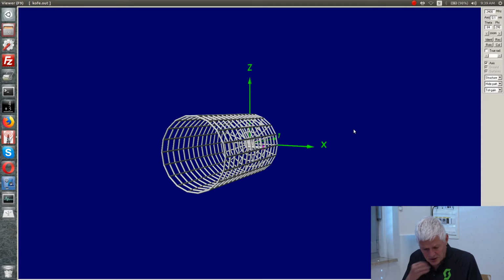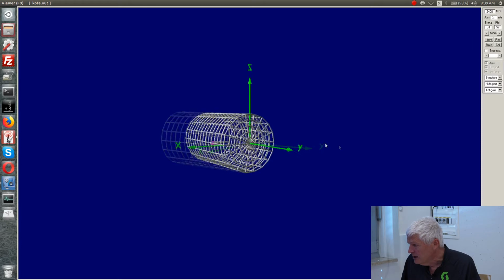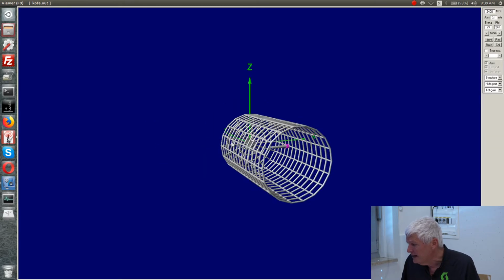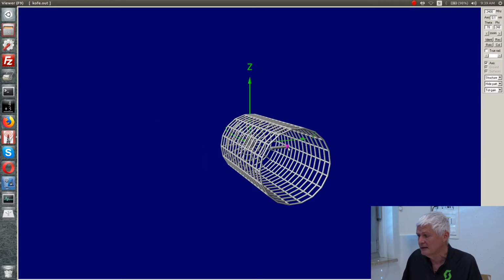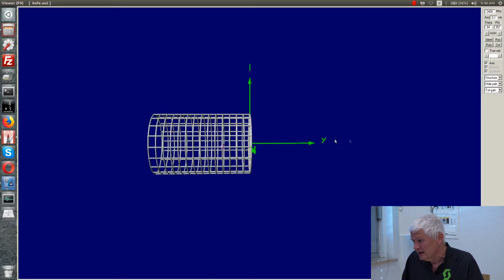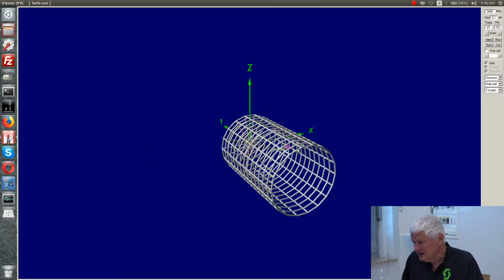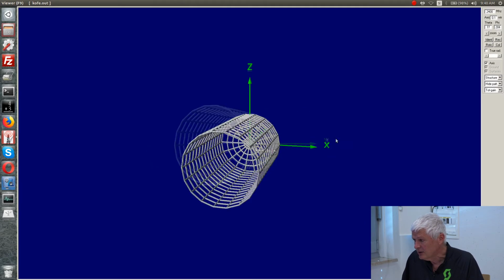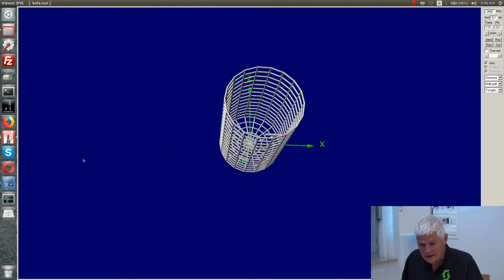Of course, we are not simulating this accurately. To simulate this accurately, we should expand this detail and have many more segments of wires inside here. We should also simulate the probe, not with just one wire, but with many wires, with a conical section of many wires, in order to simulate the impedance correctly. But this is just a simple trick to make things work with a simple program on a single computer, when we may have just one CPU core available for computation.